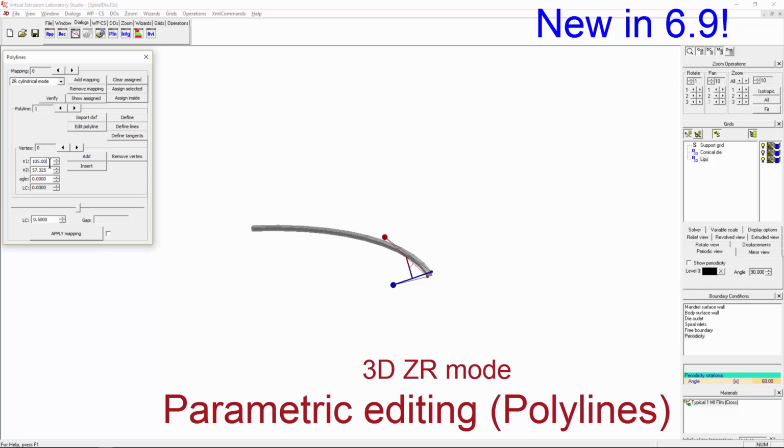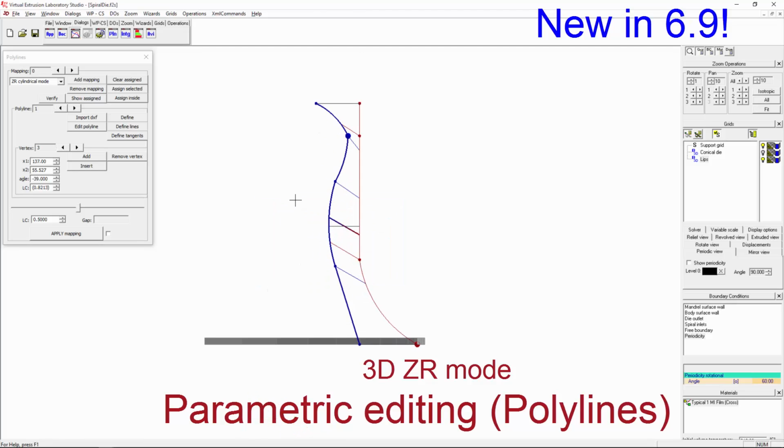The next polyline can be something like this, and then I will add a node here, and add a node here. That's enough. And for this one, I will again add a node. Okay, that's it. And I can add some radii. For this one, for example, I will use a radius and bring it there. I'm happy with this shape, so that's my final ellipse. Whether you like them or not is not important. We just want to show the principle.